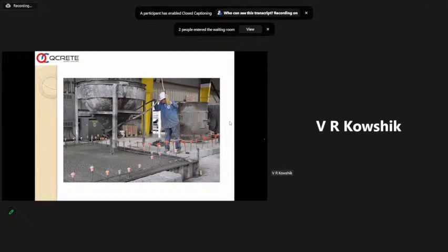And most importantly, earlier, I'm talking about until 2010, 2015, when an admixture was used for making SCC, there used to be bleeding initially, and we needed to wait for about half an hour or 45 minutes, or in some cases more than 1 hour, for the bleeding to come down.